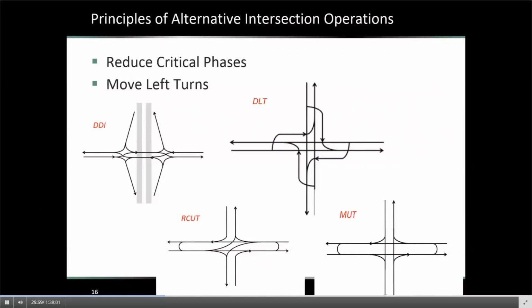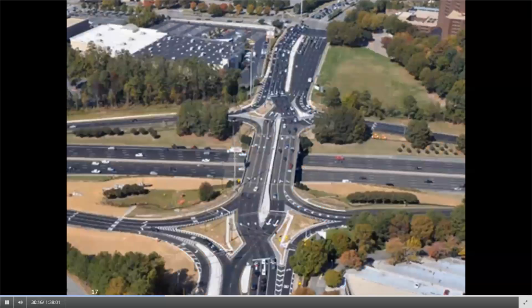And so instead of having an 8-phase signal with 4 critical movements, it really replaces those with clusters of signals, most of them managed with 2, in some cases 3 critical phase signals. So we're replacing one complicated signal with a series of clustered, very simple signals.